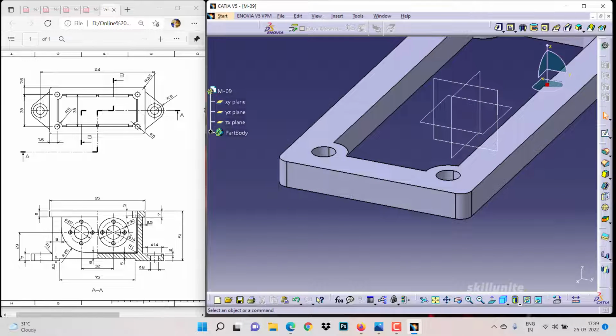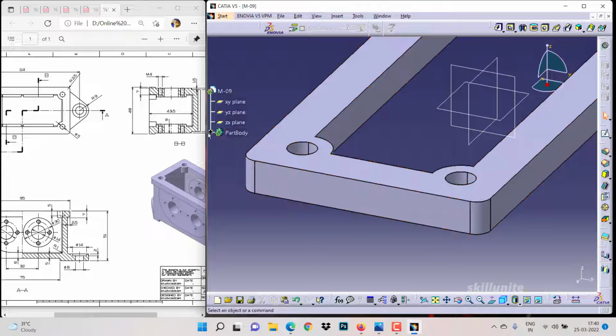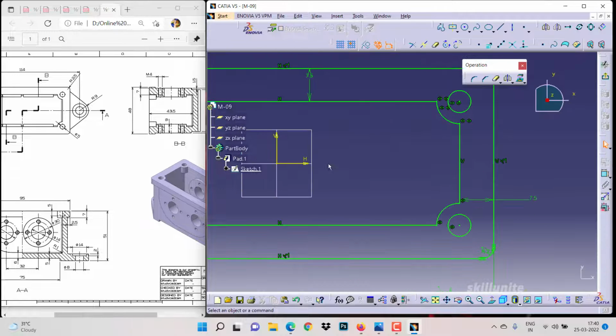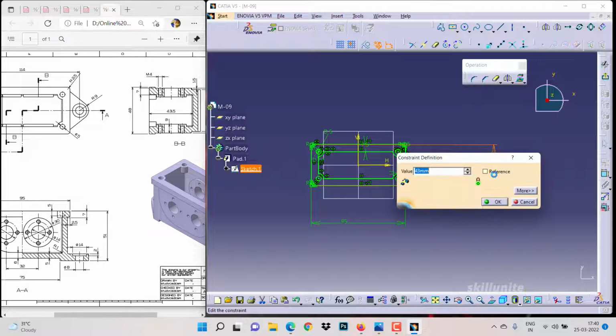The next step, we are going to create this shape that we have over here. This one we can create from the side, and extrude it together. Then inside we will make a cutout, that will be the easier way. We have to change a little here, so the width has an issue. This width total is 48 mm, but we created it with 43, so let us change that to 48.